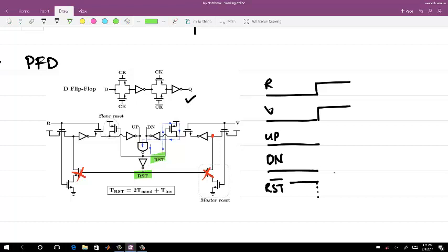So again, this is the case where, if the leakage starts happening and no one is holding the voltage, this will have a problem. But if the leakage is not substantial in the time which you are considering, then the gate voltage is not a problem. So in all the pass transistor logic, this will be some kind of issue or the other.